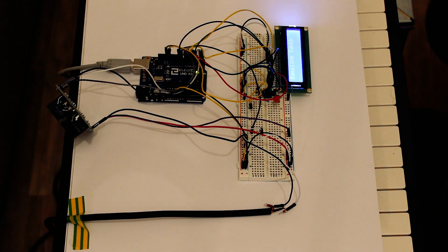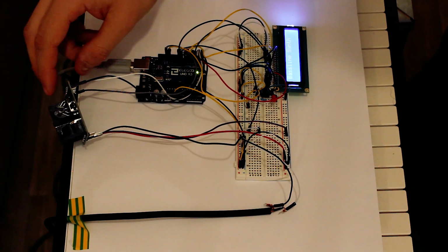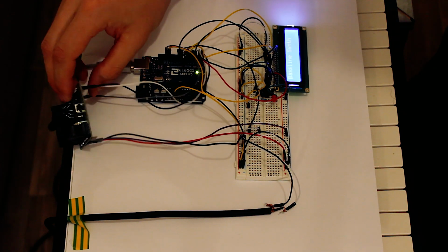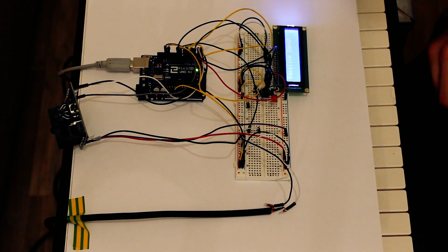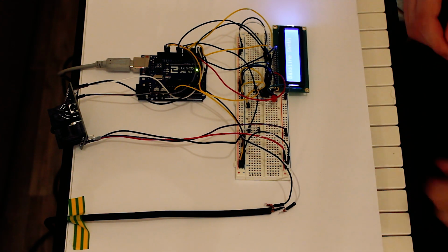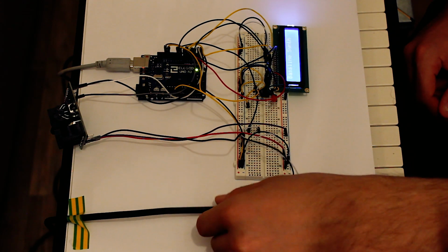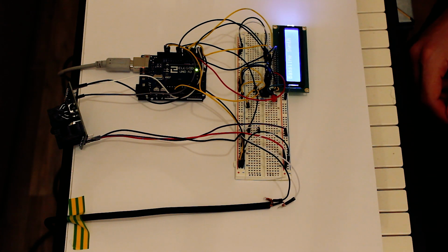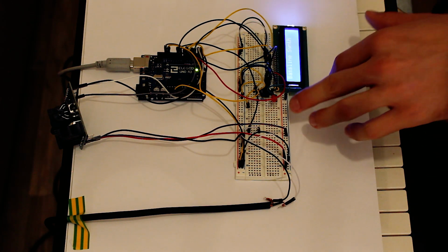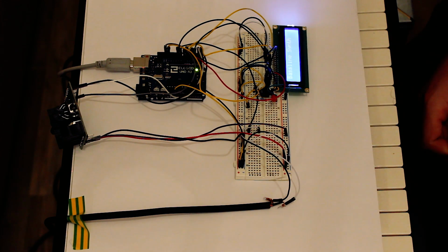I basically use a MIDI shield, which you can buy pretty cheaply on eBay, and I'm connecting the data out pins from the MIDI shield into the TX and RX inputs of my Arduino. These are the inputs that receive serial data. I also make sure to connect digital output 9 to my standard jack cable and make sure that it's also connected to ground. All the rest that you're seeing are basically the connections for the display and for the LED light in order to indicate if a note is received or not.